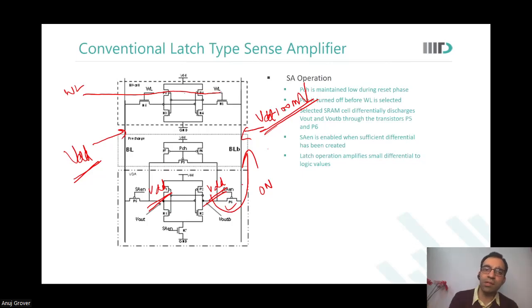Actually, the memory cell and VDD minus 100 millivolts. Okay, that's fine, but there should be a closed circuit when I operate, right? The word line is on, no? Word line is on. The memory cell is sinking that current. Where did this VDD minus 100 come from? It came from the memory cell itself, no?